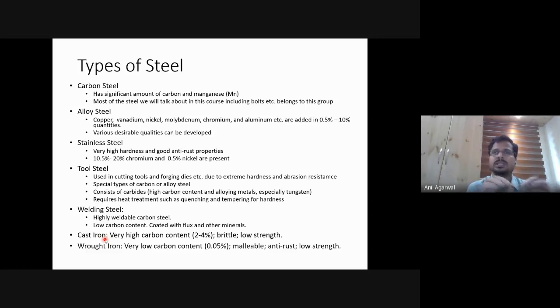So, wherever you can see a seam, if you look closely on a manhole cover, you can see that there is a kind of a seam where there was a leakage of molten steel. Which is different from a kind of a line that you will get through welding or through rolling process. So it is not made with welding, rolling, or any kind of machining. It is basically cast. So cast iron is basically you take molten iron and you cast it into a mold. Okay, so you pour that in a mold and you get that shape. So that's how cast iron is made. And you don't do any processing after that.